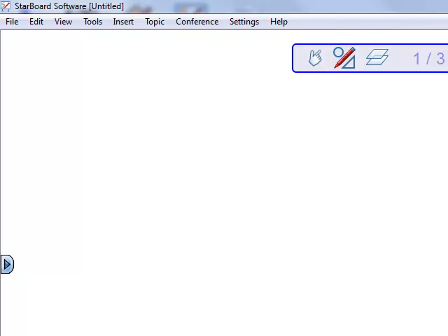Fabrication detail is an important term to remember, as used in structural steel drafting. They are the orthographic drawings of structural members showing all information required for fabrication. And the primary component of a shop drawing is the fabrication detail, which is what you're going to draw with this assignment.